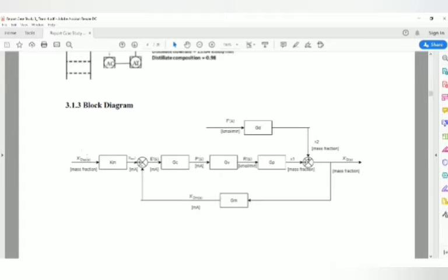Starting from XD set point, we will go to sensor, and then error will be produced by the comparator to controller, and then from the controller we produce electrical signal to valve, and from the valve we produce reflux flow to the process transfer function, and then the output will be the changes of distillate methanol composition. From the disturbance transfer function, both of the outputs will produce a new distillate.